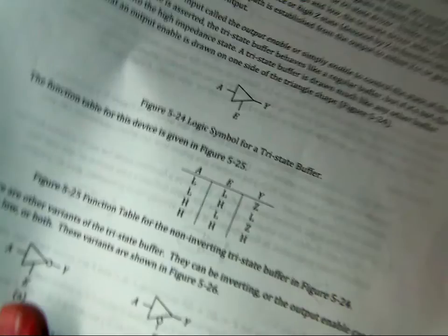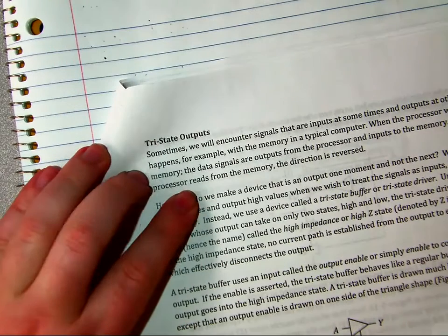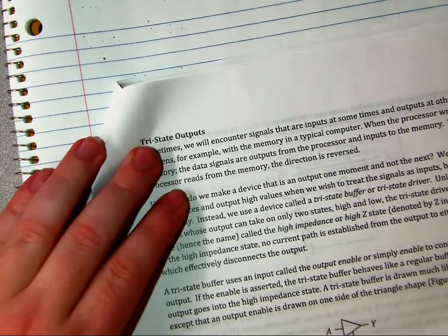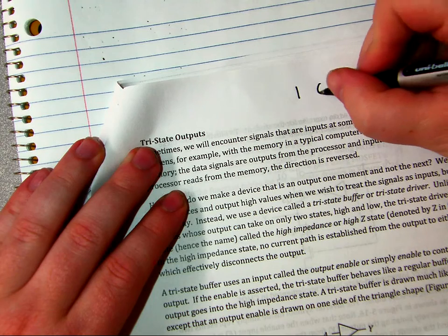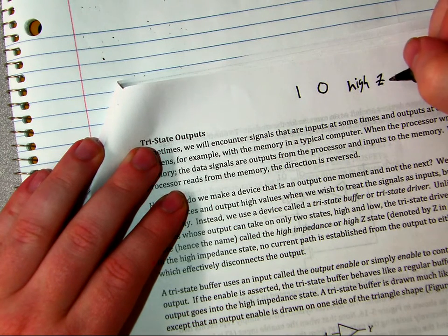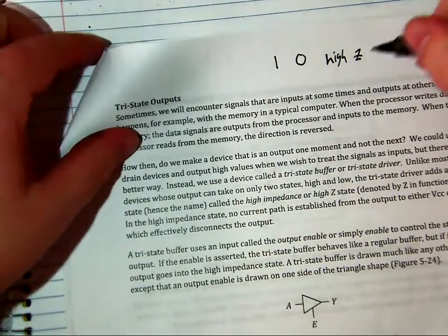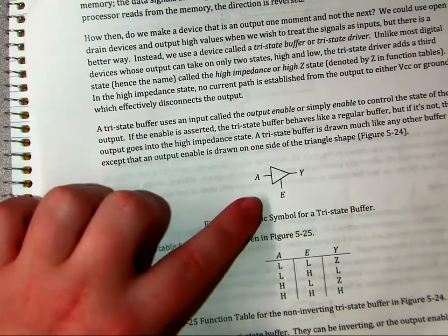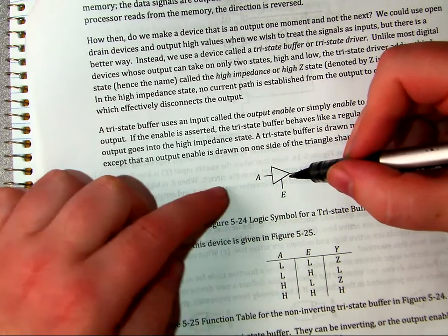A more useful concept is tri-state outputs. What tri-state outputs do is they add a third idea where you can have either 1 as an output, 0, or high Z, or high impedance. So Z is kind of the symbol for impedance, and just because impedance is a big word, I guess. And so we say high Z. What that looks like in, say, a buffer is there's a third signal that is enabled, right? So I can turn it on or off.